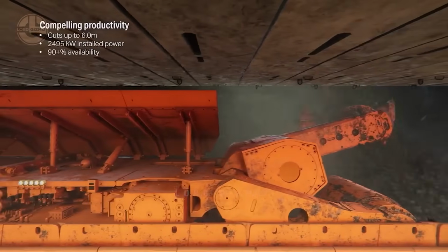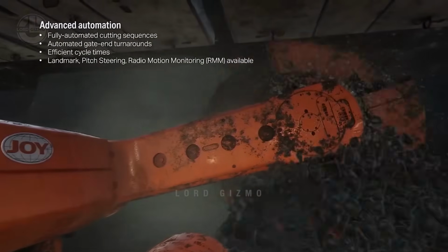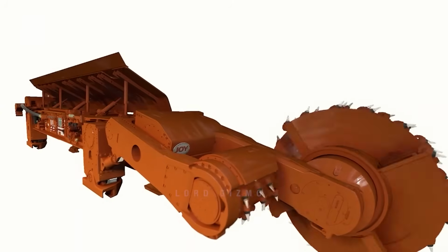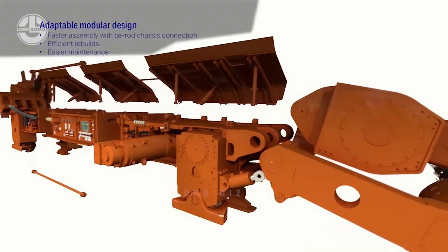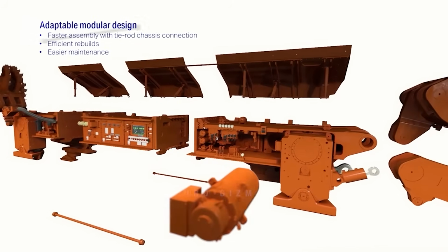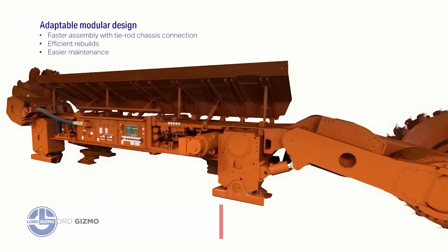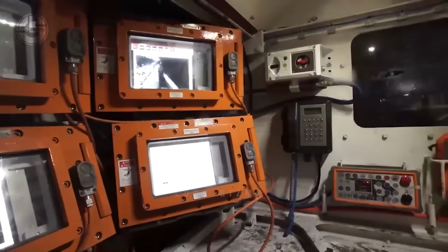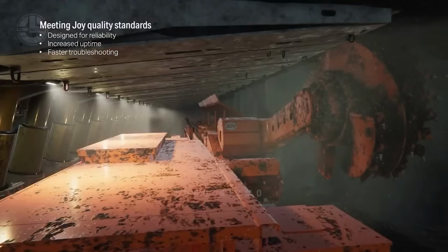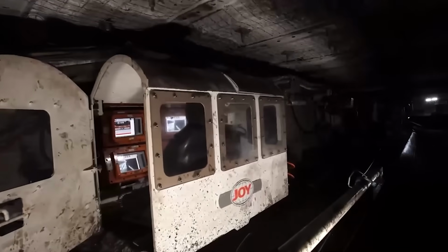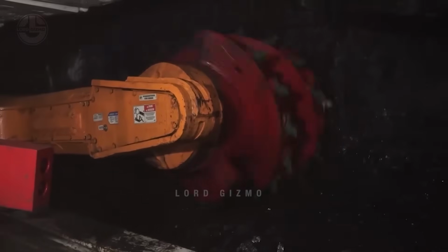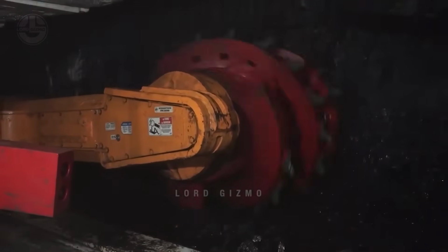Longwall mining involves a highly mechanized process of removing a large panel or block of coal in a single slice. The main feature of longwall mining is the longwall shearer, a large machine with a rotating drum that moves back and forth across the face of the coal seam, cutting the coal, which then falls onto a conveyor for removal. The entire operation is automated and includes advanced roof supports to protect the miners. This method is highly efficient for extracting coal from thick seams, but requires a significant initial investment.